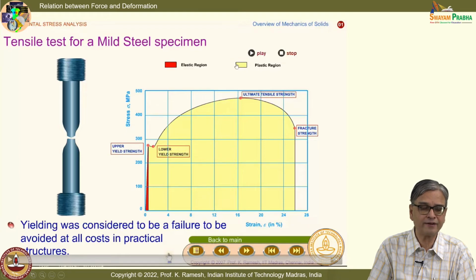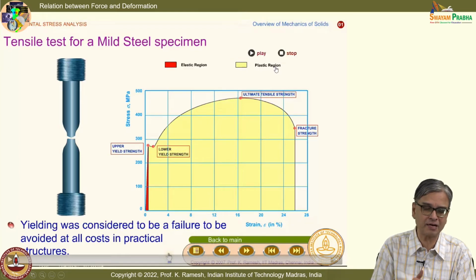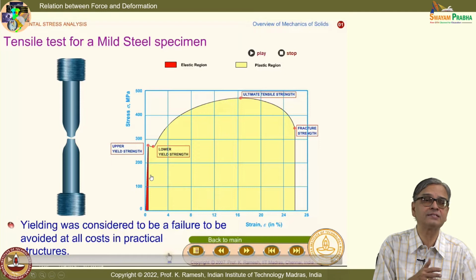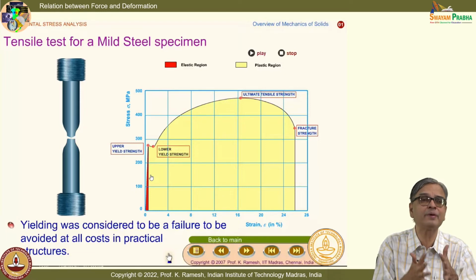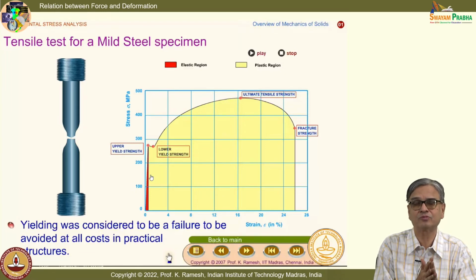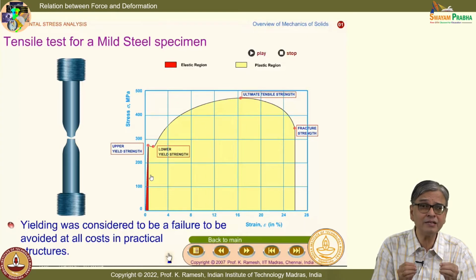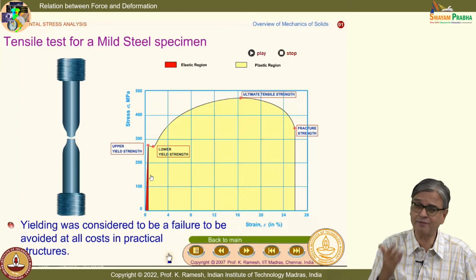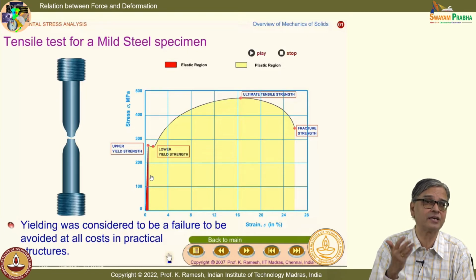This would be required if I have to design a crash bar. I would like to have a good plastic region, and many of the engineering components work together, so they have to remain in an elastic region. So, from a practical perspective, we will live in very small deformation in many of the applications. In some applications, we will have to go to large deformation, large plasticity and so on, but those instances can be handled as special cases.